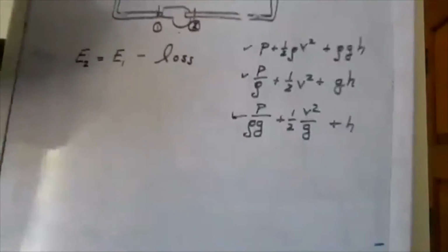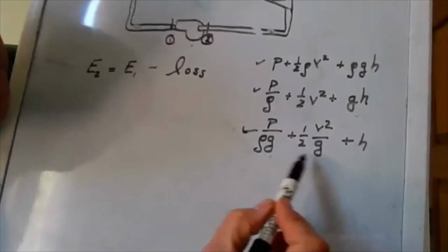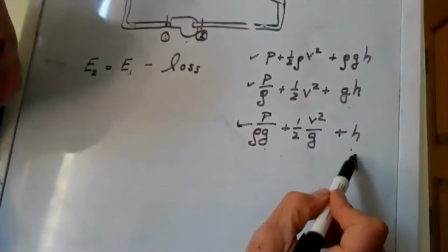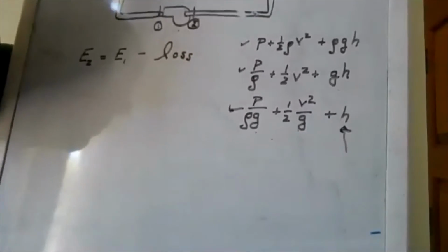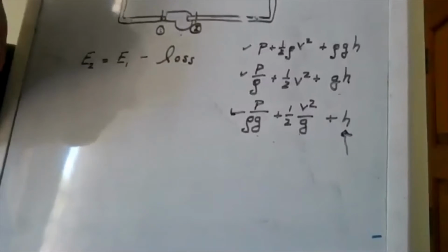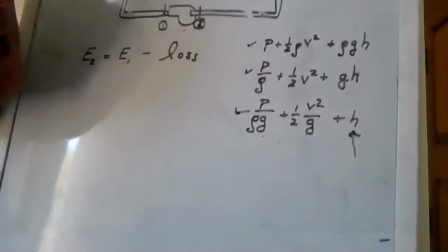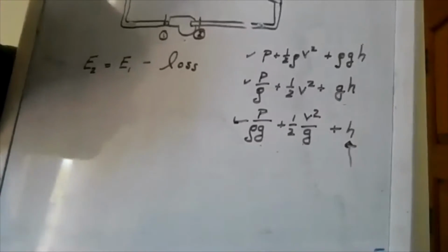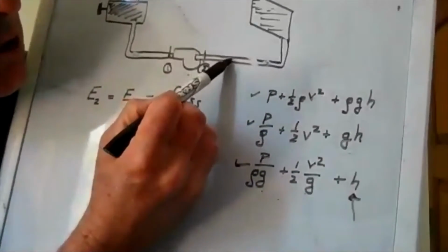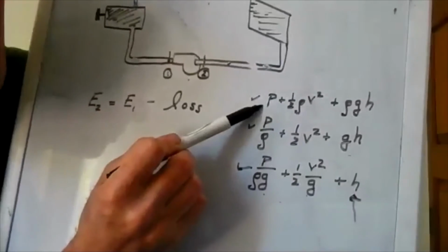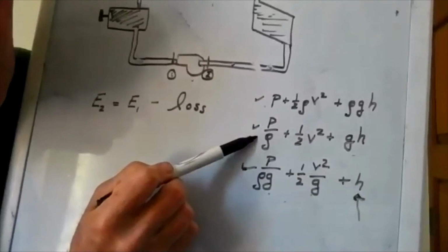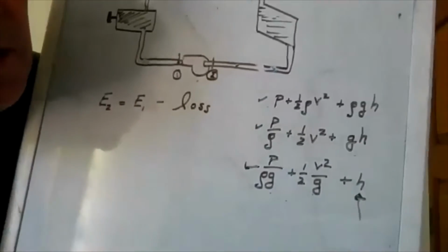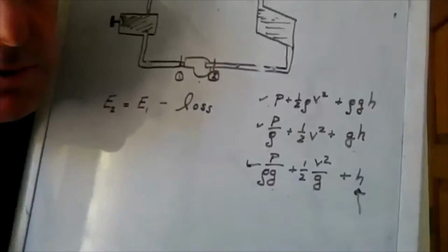Okay, so here's the third option, is that we can express these three terms as shown right here. Okay, what are their units going to be? It's going to be easiest to take a look at that term right there. What are units for h? h is like a height, okay? I could have used z, by the way. And so our units, if we were in English units, would be feet, equivalent feet of water. So we can think about the energy of a fluid in terms of its pressure. We can think about it in terms of its joules per kilogram, or we can think that that energy the fluid has is equivalent to a certain number of feet of water.